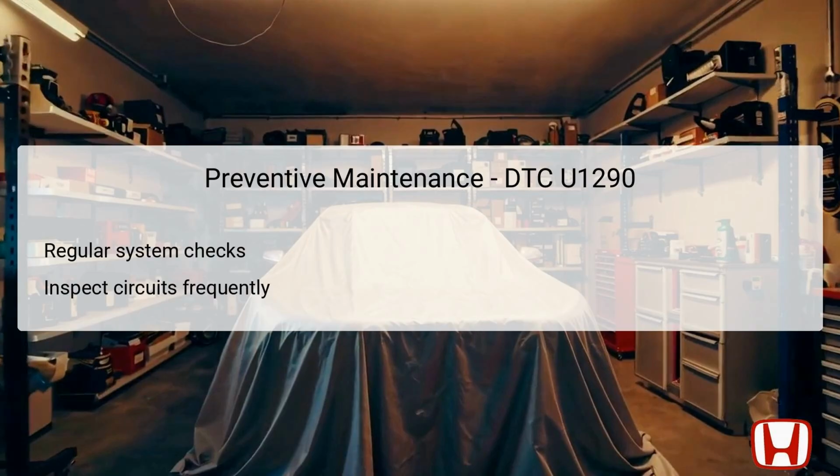Additionally, inspect the climate control unit and front seat heater control unit for any error messages during diagnostics consistently. Keeping battery terminals clean and ensuring good ground connections can also prevent disruptions in system communication. By implementing these maintenance practices, you can enhance reliability in your vehicle's electrical systems, contributing to overall vehicle safety and comfort.